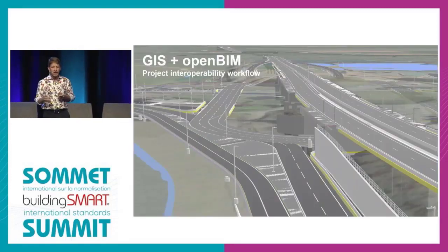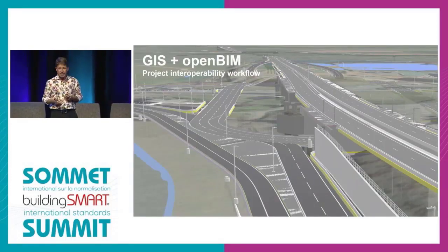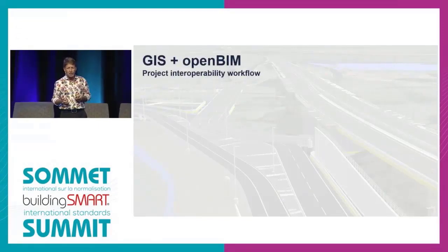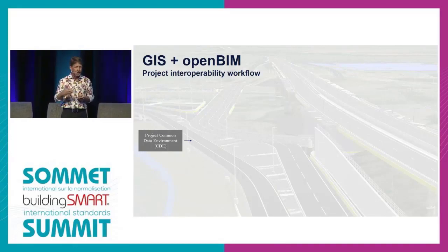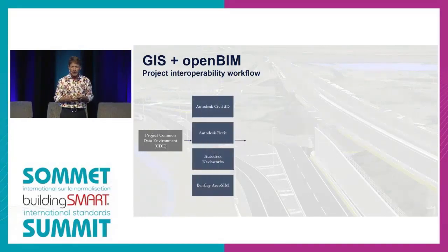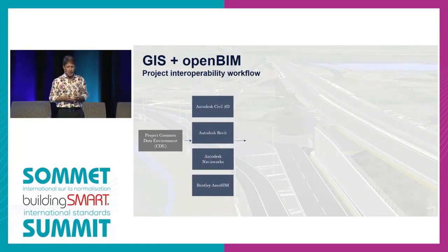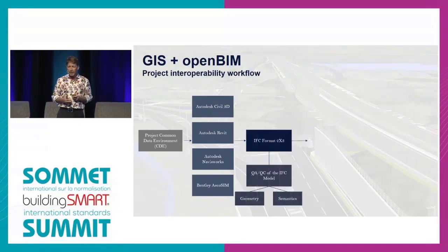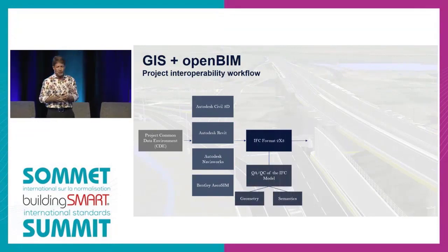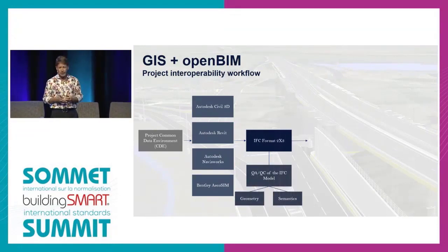And in this project, openBIM is core. Their interoperability workflows, they start out with the idea of a common data environment or a connected data environment made up of various repositories, fed from Civil 3D, fed from Bentley AECOsim, visualized with Navisworks, Revit content, all brought in. But everything then gets converted to IFC, in this case 2x3.